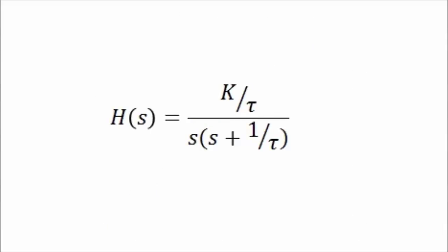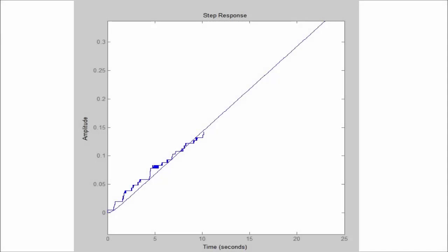And then we approximate the transfer function to the system seen in class, which is a level control system. This system is H(s) = (K/tau) / (s(s + 1/tau)). We tested different values of K and tau to get a transfer function which approximates our plant response. According to the graph, we get H(s) = 0.03 / (s(s + 2)).